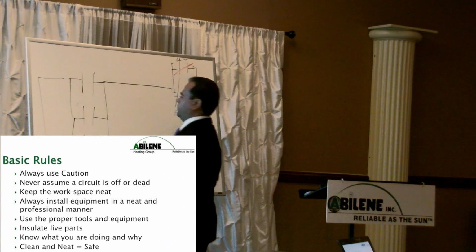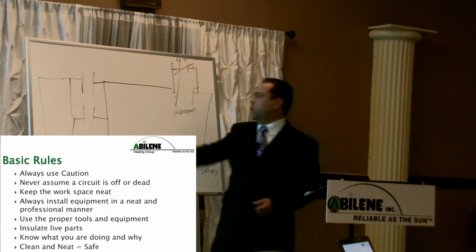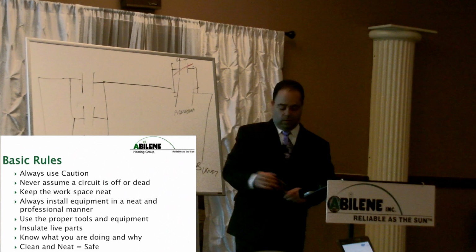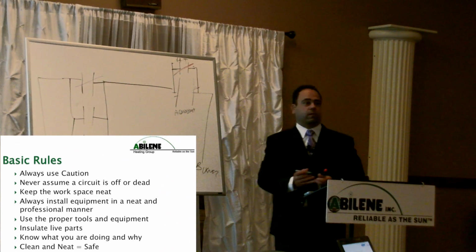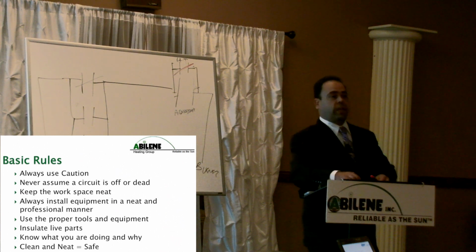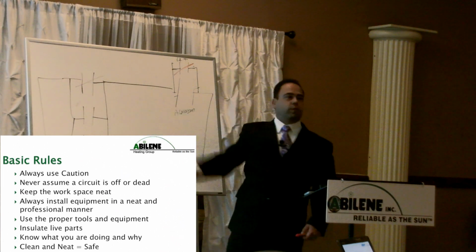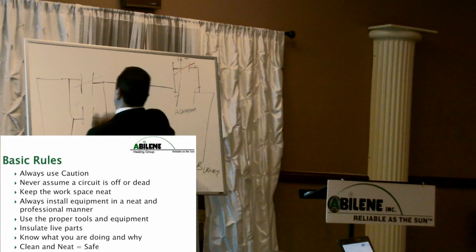right? They're all in parallel. One could be a low water cutoff, smoke alarm, or pressure control. If any one of them is made, it's going to fire the burner. That's a mistake, right? Because now if I run out of low water, the burner's still firing. Okay, the limits have to be in series.